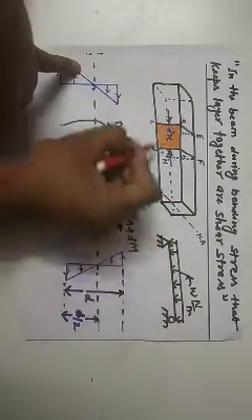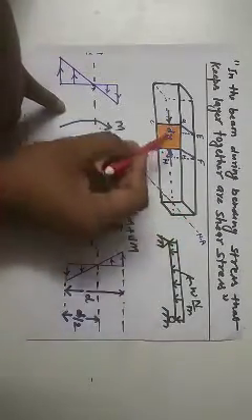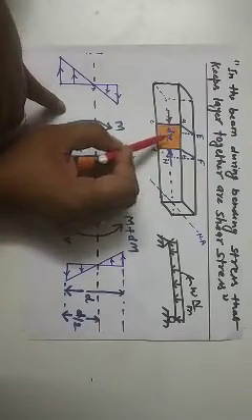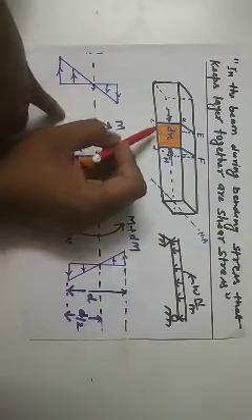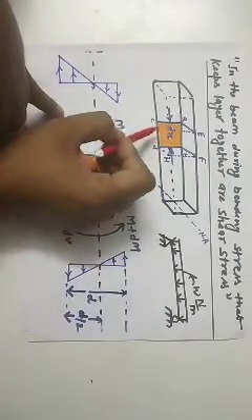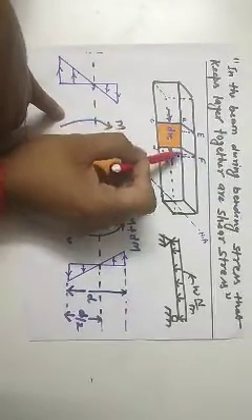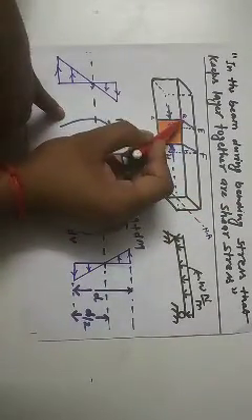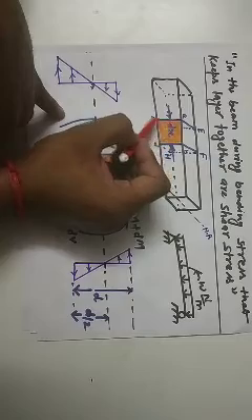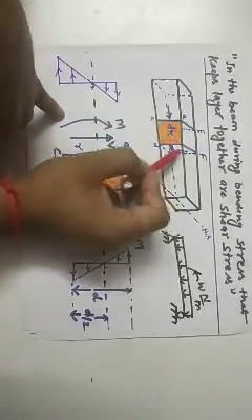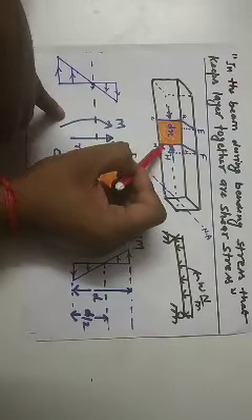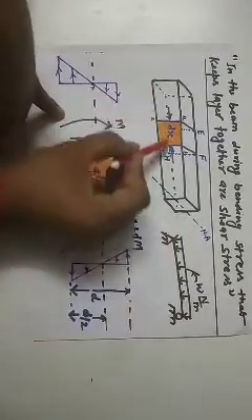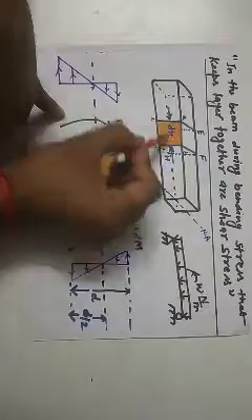Consider a beam. This is our beam, and we have considered a small length dx for the analysis of the shearing equations, right? Now this length dx is under observation. Length is AB, length is dx, and the portion is ABCD. The cross section of the beam at portion AC is ACEG. G is hidden, and the cross section at BD is BDFH. BDFH, right? This is the neutral axis, and here the horizontal centroidal axis along the longitudinal axis will be the neutral axis line, right?